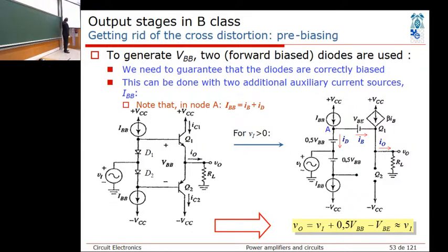One diode has about the same drop in here as here, especially if you run a biasing with a current source. So basically that will shift the signal or the current biasing so that you get exactly 0-point match.